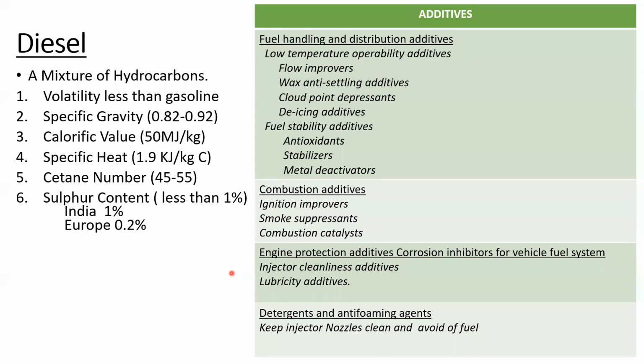So the first section discusses how diesel fuel works in lower temperature areas, such as countries like Alaska. They have to have a different setup in the vehicle in order to drive it. In most of these countries, there are even heaters situated inside the fuel tank to get the fuel up to temperature before the vehicle starts, because otherwise the fuel flow and everything will not operate properly.